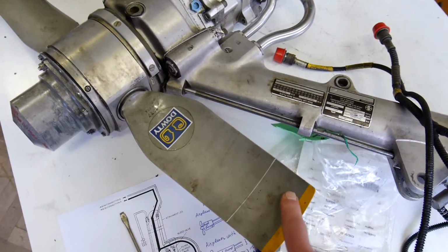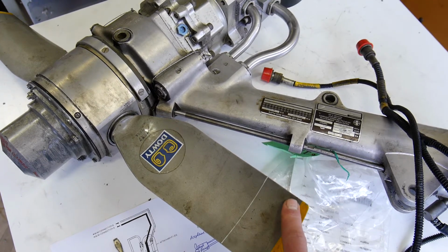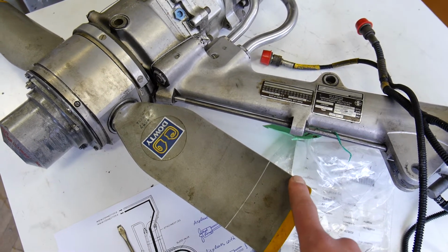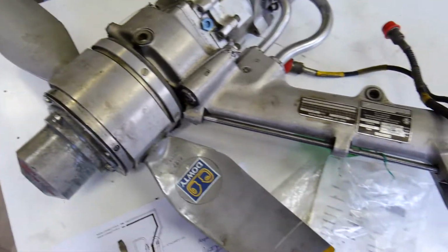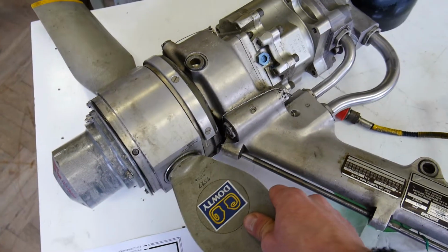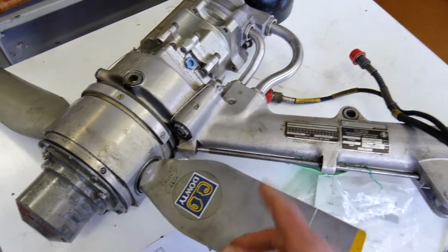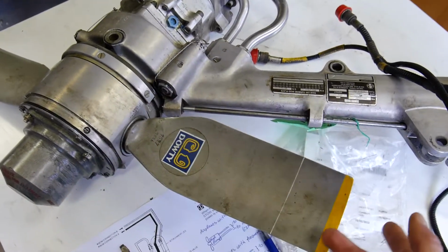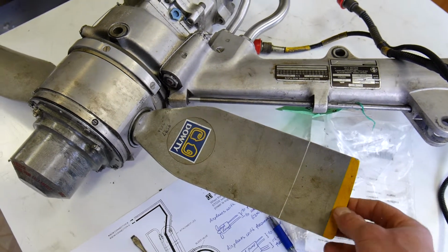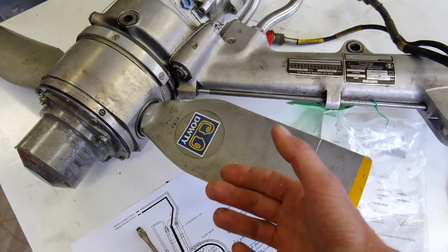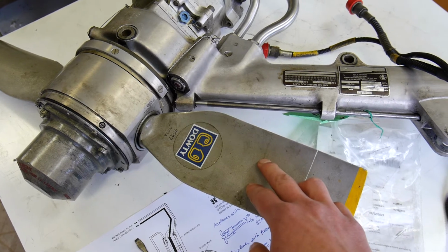So this is the general reason why it is not possible to put it back when it has been deployed during the flight. Because the blades will rotate, and they can be stopped in some position which is not aligned with the slot, which is in the wing or in the engine nacelle. So we can't stow it back, because the propeller is not aligned.